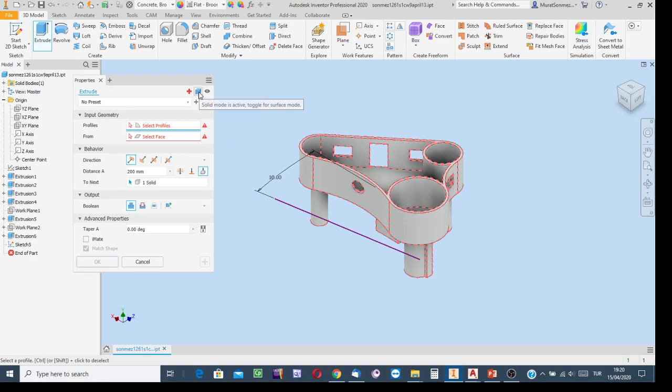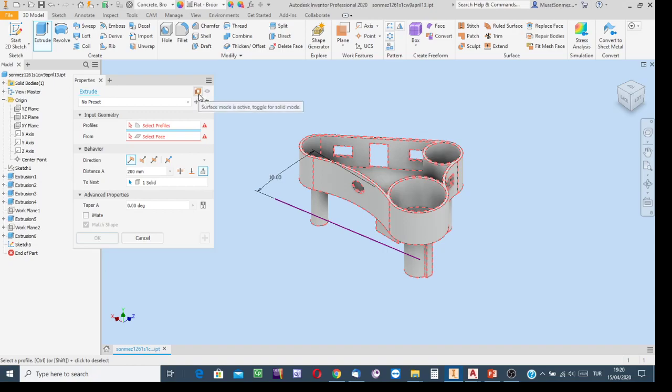Bring the cursor onto this one and change the mode. Click on this and then select surface creation mode. See the symbol on the button now. This is to imply a solid model, but this is to imply a surface. After changing the mode, the extrusion process is now ready to apply for creating surfaces. Then indicate the sketch with a click.